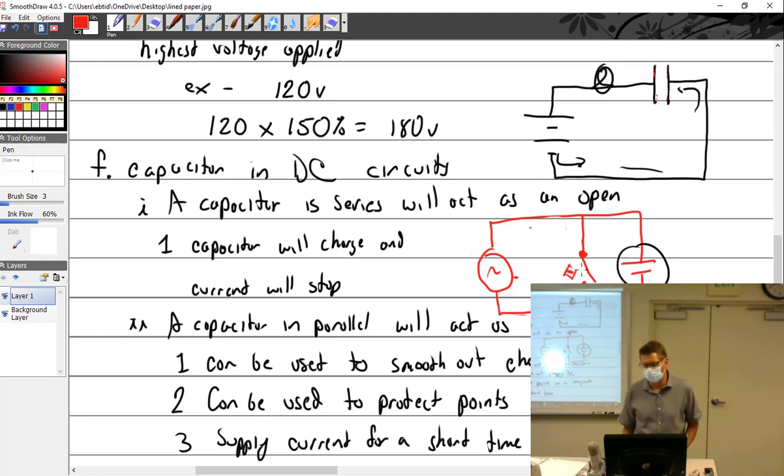So this cam turns around and it opens these points. They open, close, open, close, open, close. And it's going to do some other stuff down on the circuit here, which is going to make a difference in what's going on right here. What's happening further on down the line is not important right now. But we're talking about a lot of voltage going through here, in the thousands of volts, very low amperage. When you have a whole lot of volts, you can jump gaps. These points are just a switch vibrating very fast inside this magneto, making the circuit go on and off rapidly. There's a lot of things you can do with that, but we'll talk about that next week.